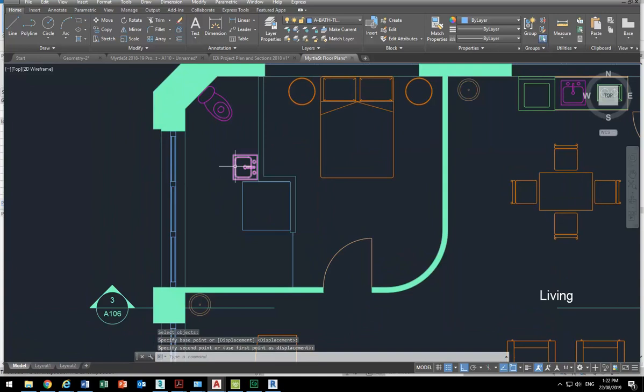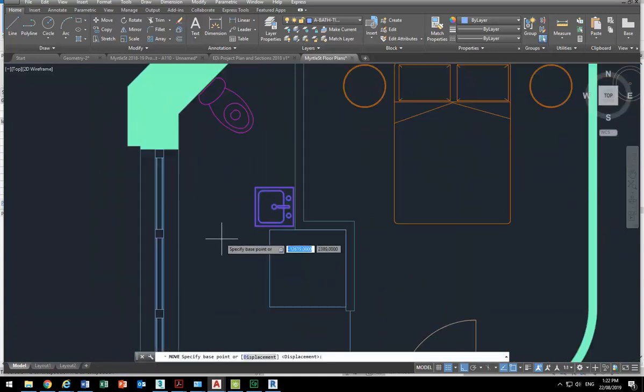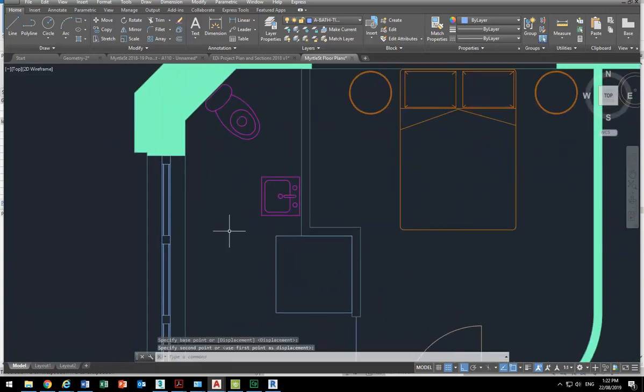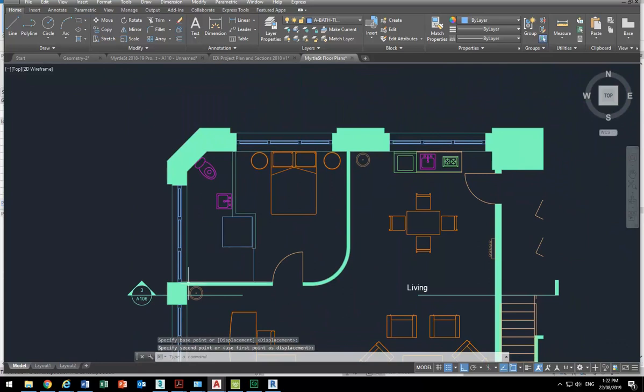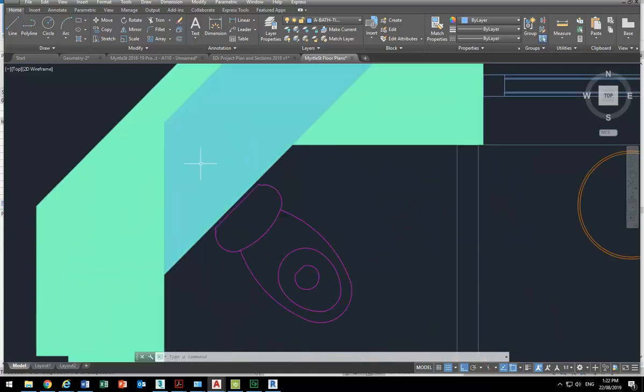So that's the way you want to maybe start to set things up. Just get your basic planning to work, and then that'll give you an idea about the requirements for your services. So the big one, of course, is the toilet. It needs a big drain, so you've got to have a riser for that. Here you could definitely look at having it in that wall.